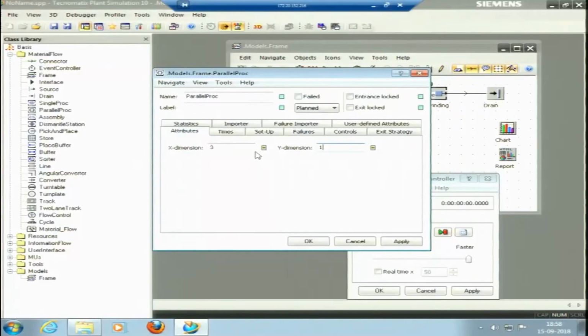So, it was waiting for 40% of the time. If we put 2 machines at that successive point, this 40% of time will reduce to 0, okay, because now the processing is doubled here. So, in that case we can think of putting parallel processes. When there is a waiting, when there is a blocking, we can think of adding new machines, or of taking a few machines off.